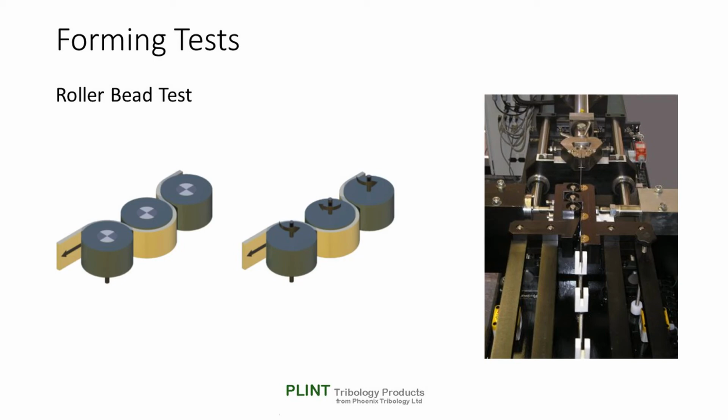Having completed a series of tests with the rollers fixed, a series of repeat tests are performed with the rollers free to rotate, with the same clamping force as established for the fixed bead tests. The assumption is thus that the measured drawing force with fixed rollers is the sum of the friction force in the tooling and the deformation force, whereas with rotating rollers the drawing force is the deformation force only. Friction coefficients for the test series can then be calculated.